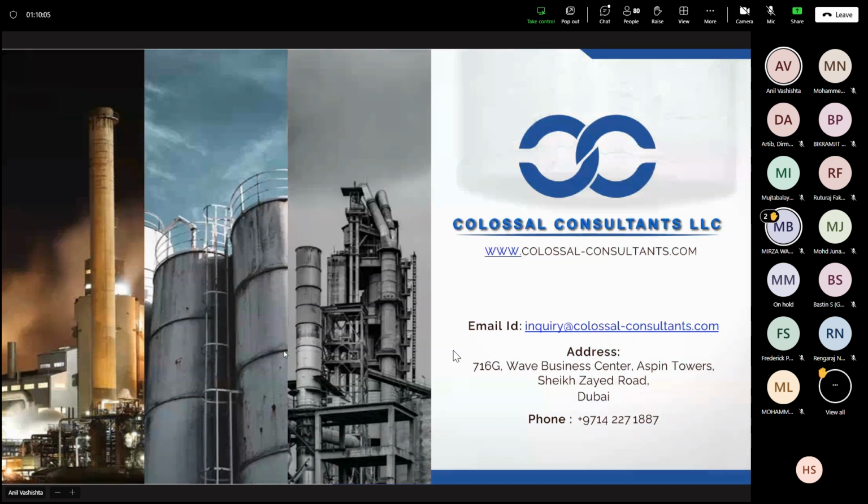And when you do the investigation, you will see where the failure has initiated. You can see the initiation point very clearly in the metallurgical examination. If it is a fatigue failure, you should be looking for features related to fatigue, notch and stress concentration. So if it is a stress concentration like notches or a pit depth, that has initiated the fatigue failure. So this is just with reference to fatigue.